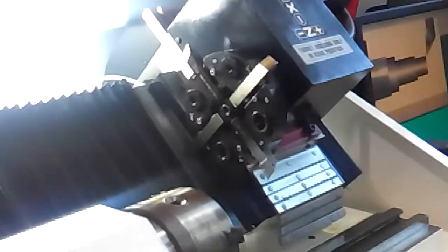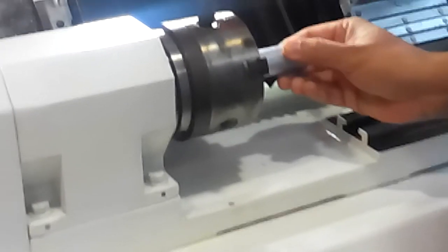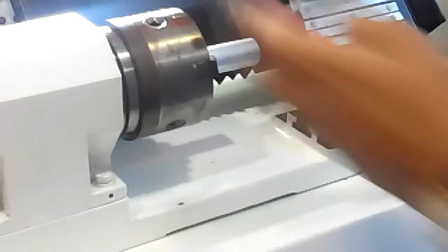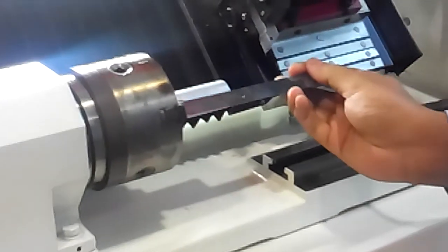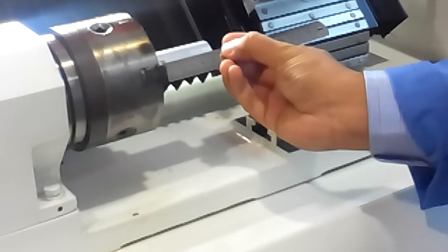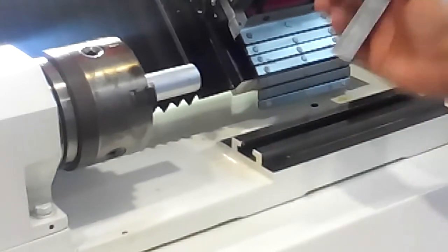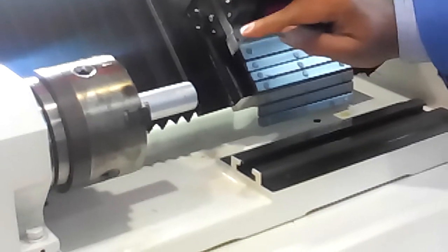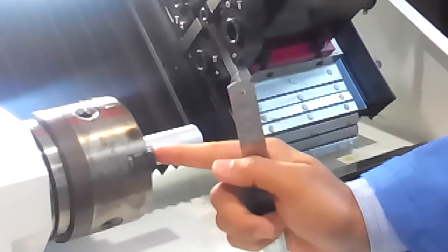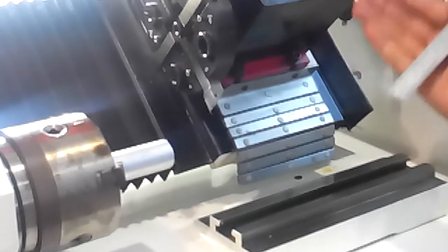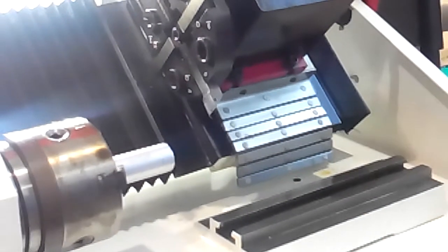Once the tool is there, clamp your workpiece. This is the chuck, and this is the chuck key. Open this one, put your workpiece inside, and make sure it is projecting out as per your workpiece length, and measure this length. Is it okay or not? If you are going 50 millimeters deep, at least you should have 5 millimeters extra. Why? That's the safety thing. If in the program you put 55, the tool will go and hit the chuck. That's what we have to take care of, so that it's not damaging the chuck or the machine or the tool. So this is how you clamp the workpiece.